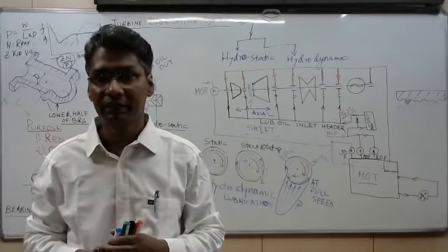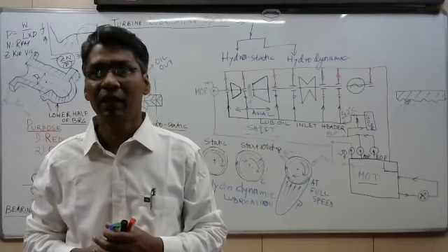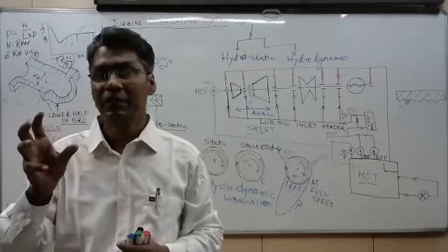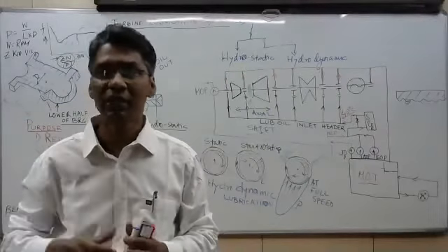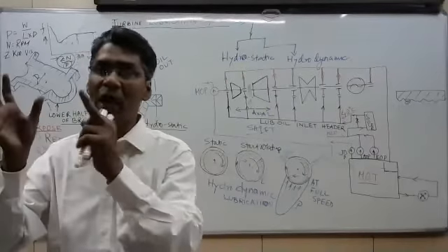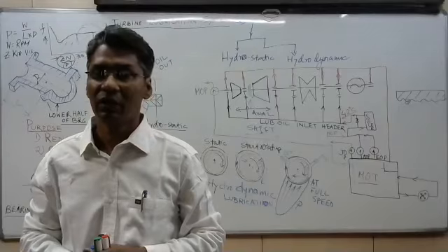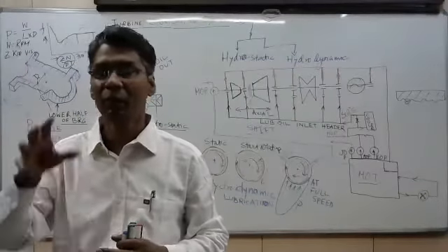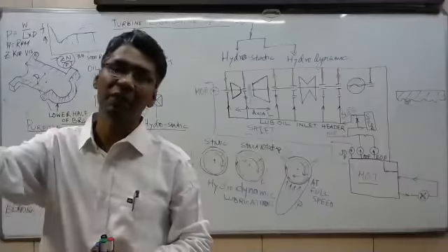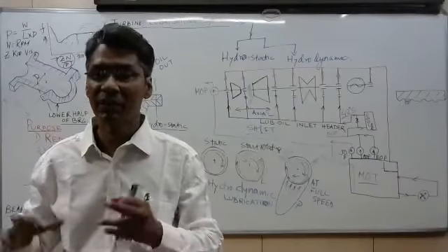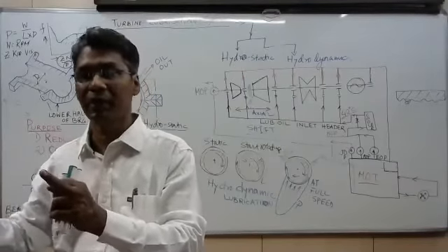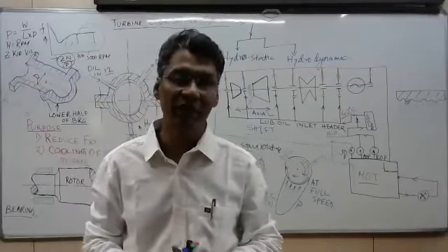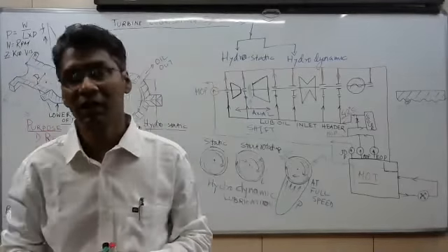Ajit Kumar Singh: why is oil pressure different at all bearings in the turbine? Maybe the pressure is different due to the different size of orifice fitted as per the quantity of oil required. See, pressure is not important, the quantity is important. If you reduce the quantity of oil, the bearing temperature will go high. So as per the requirement of oil for the particular bearing, we design the orifice. After the orifice, maybe the pressure is different.